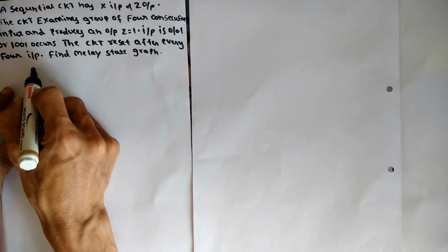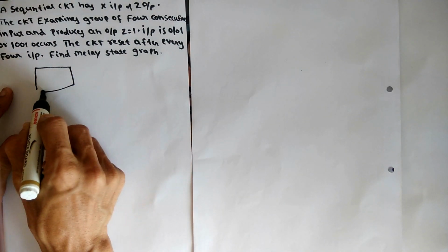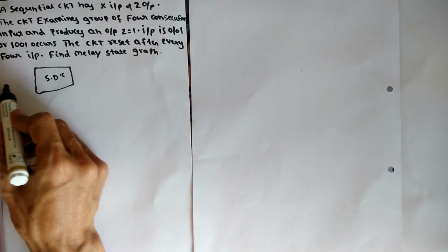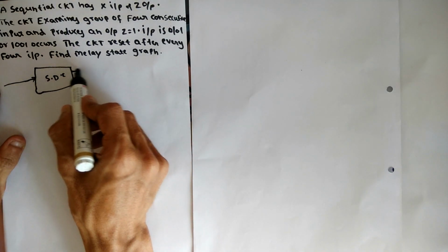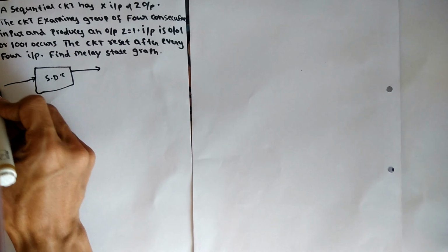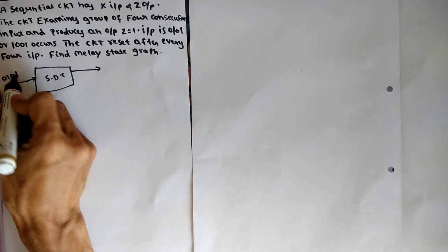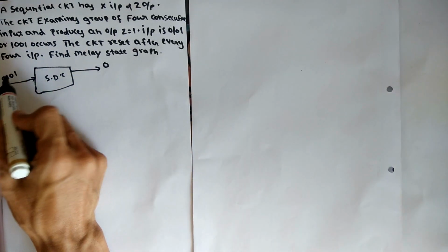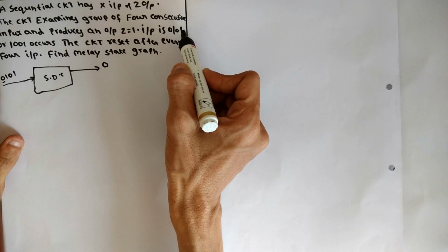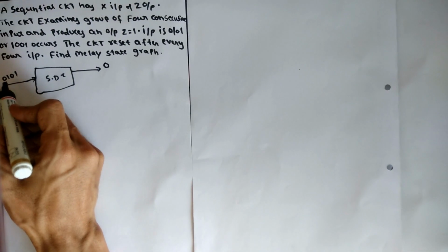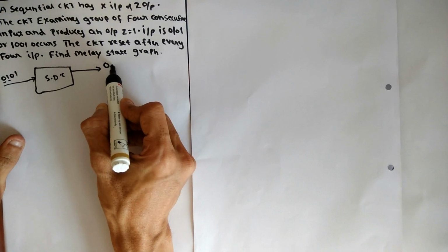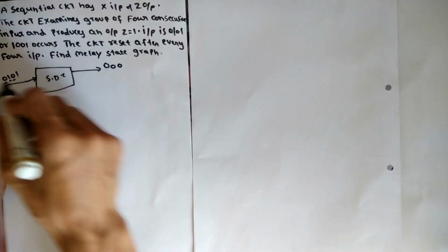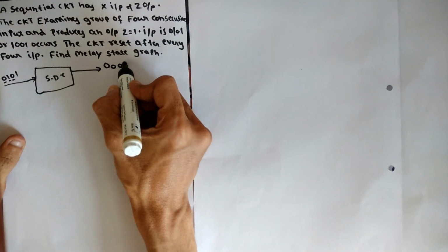So this is the usual diagram you can take. This is the sequence detector circuit, and we have to find how it should be. If you give X input something, according to that we have to get Z. Suppose we take one example, 0 1 0 1. First 0, anyway our Z is 0 because it is not a full sequence. Because 0 1 0 1 is complete only after the 4th bit, we get 1. For the first 0 and 1 we do not get an output, so 0 0 0, and then 1 means we get 0 1 0 1, the sequence is complete, so Z is 1.